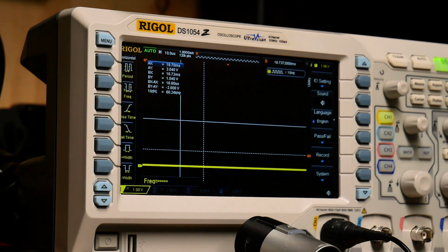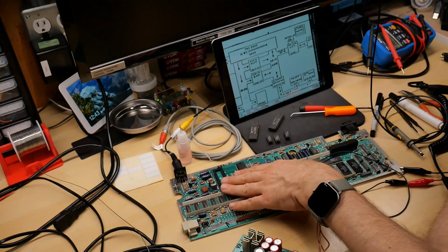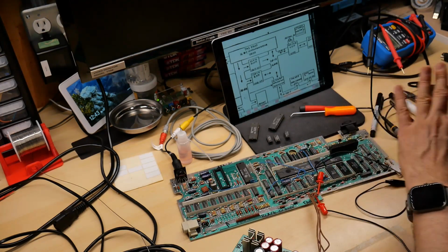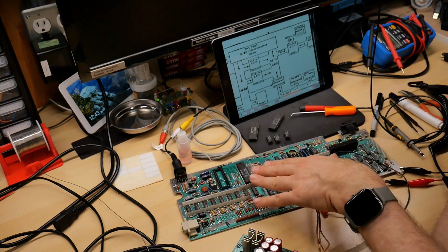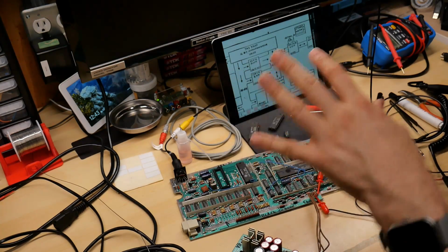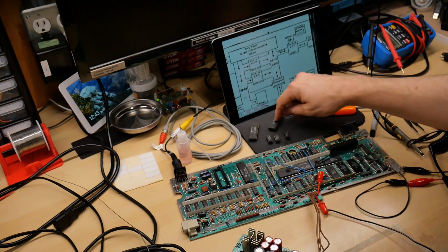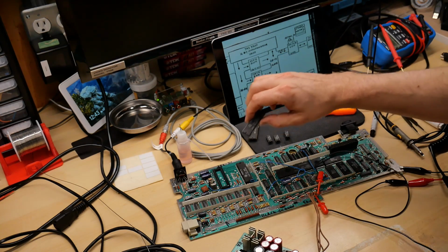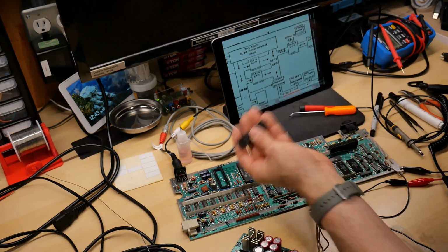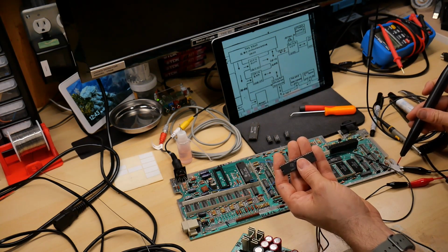Oh, I just had a thought. You know what? Okay, so I think taking out the video display processor has caused the computer to not do anything at all, because I'm pretty sure this generates the clock signals or something that's used for operation of the computer. So without this, we get nothing. So what I'm going to do is I'm going to reinstall the original chip, not the one that I've changed it out to.